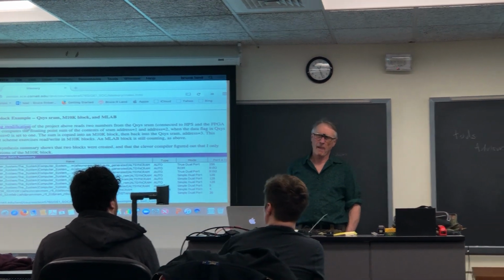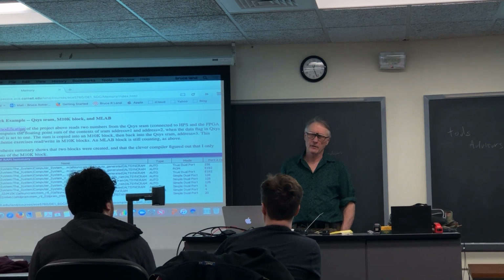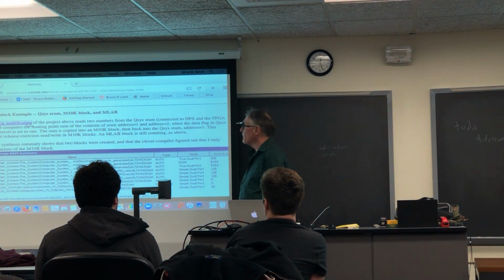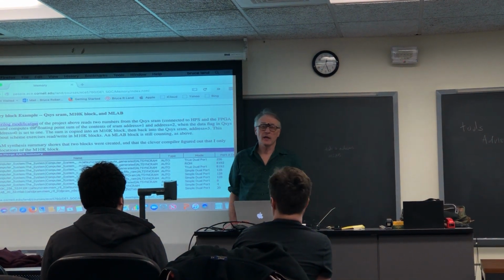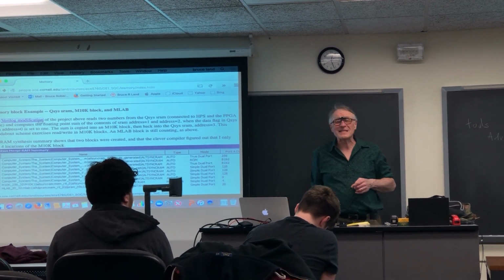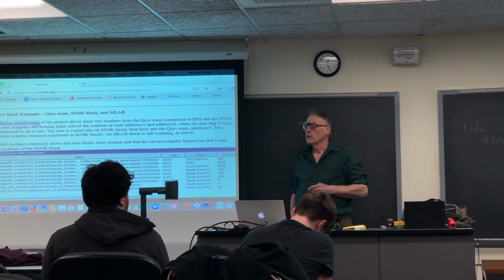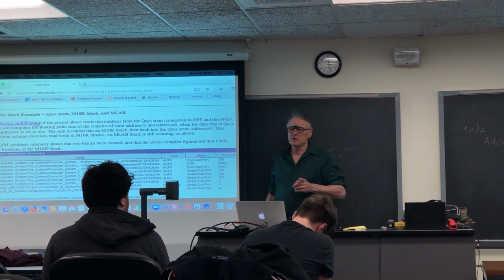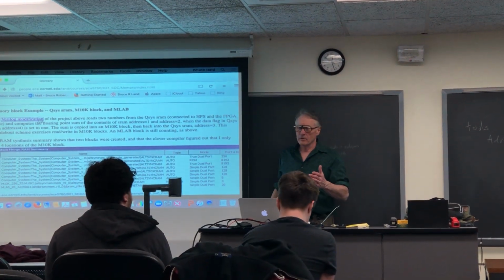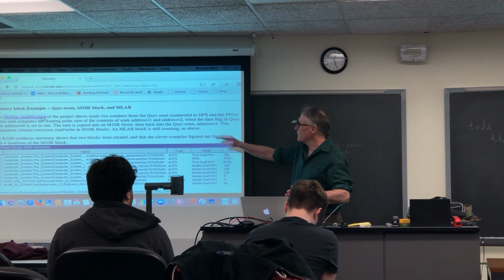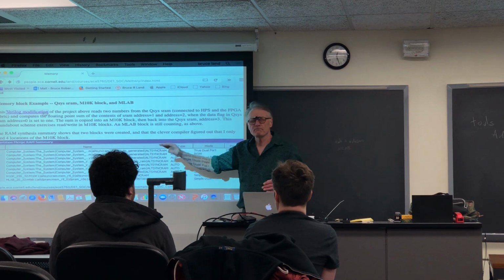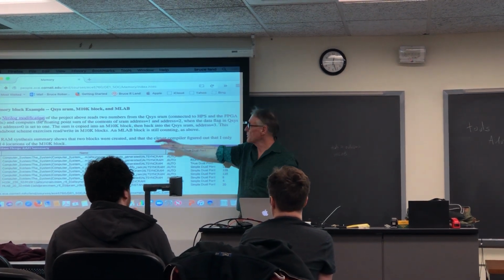Yes? So what is the advantage of an M10K block and MLab block? The advantage of M10K and MLab is that they're much denser than logic element memory. I believe that you have about 140 kilobits of memory if you use logic elements. You have about 400 MLab blocks, each of which is 32 bits by 20 words.